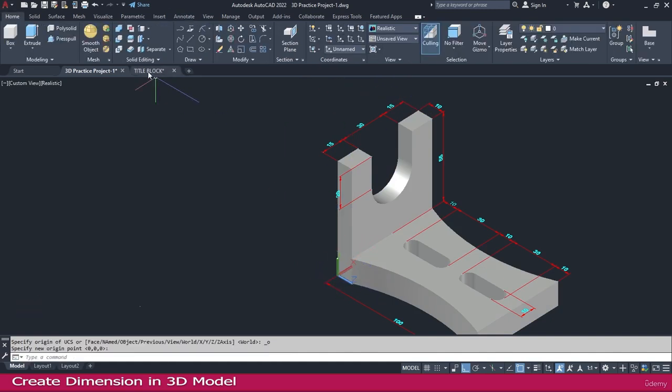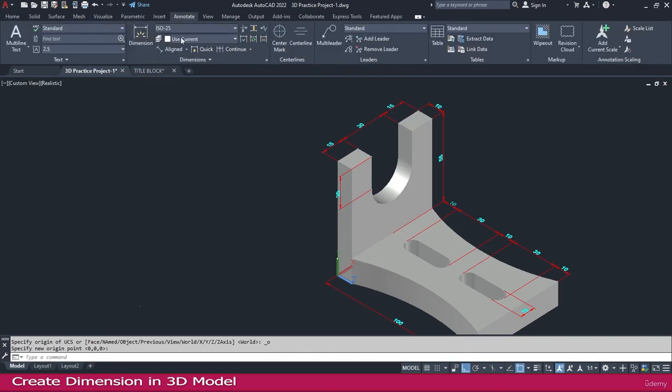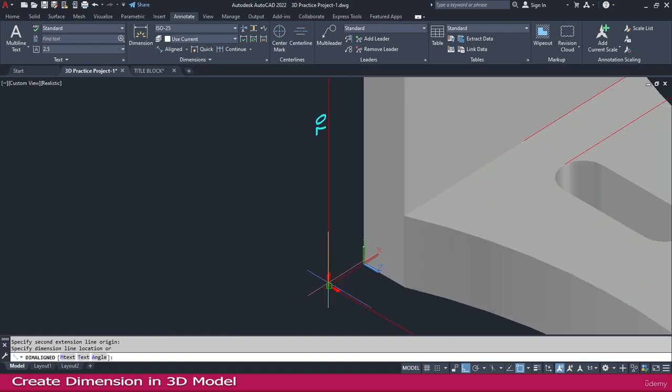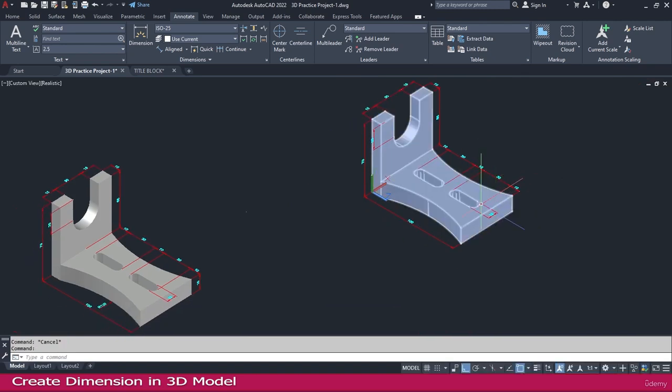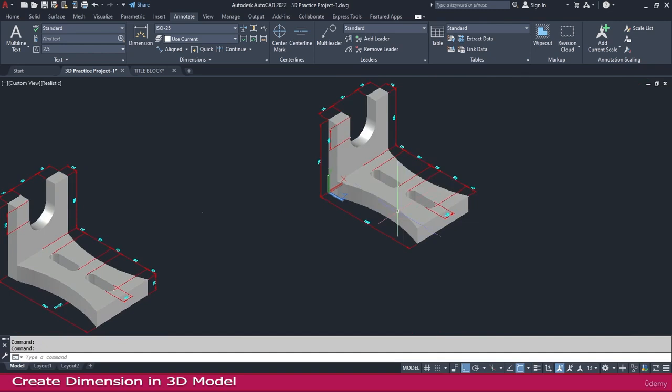And if you need to make a dimension here, just go to the origin and I place it like this, and go to align, click this point and click this point. You can place it like this somewhere else. So now it is ready. This dimension, everything is ready. Now we need to make only one more dimension, this one and the radius.